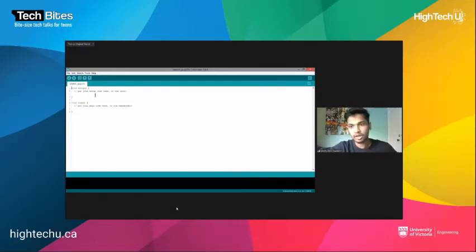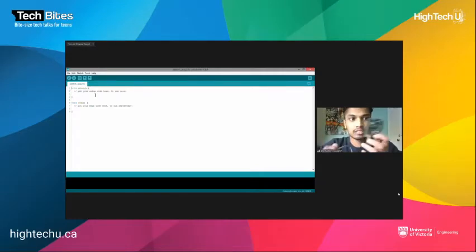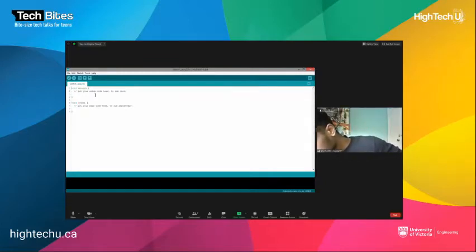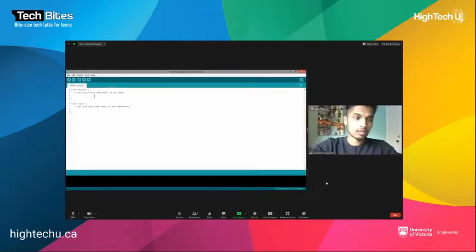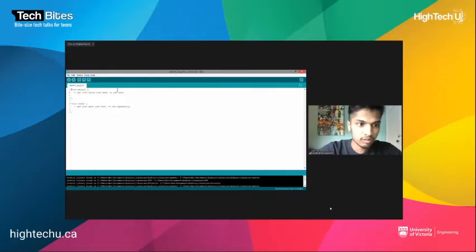So right now, I have an Arduino with me, and we are going to write a code. It has an internal LED which we are going to blink. Starting with the board, I'm connecting it to my laptop using this cord and the USB port. First is selecting the port: go into Tools, and you select the port that you can see, that is COM26 for now.